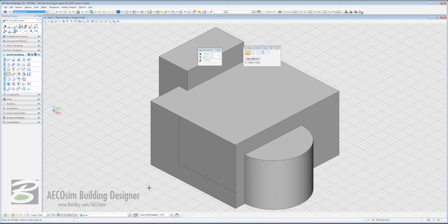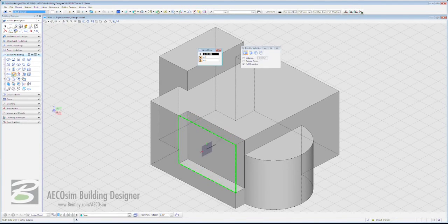That's actually just drawn a line on our solid, but more than that, because now if we come to the next icon next to Draw on Solid, Modify Solid Entity, you'll see that if you click in the middle of that square, you can now just push and pull. It's almost as if we'd taken a cheese wire to it and actually cut portions out.